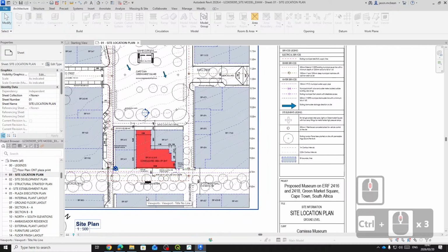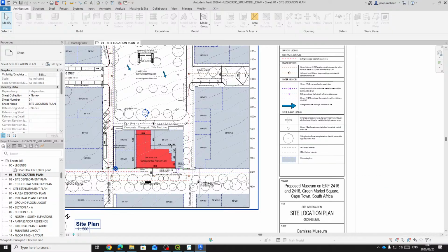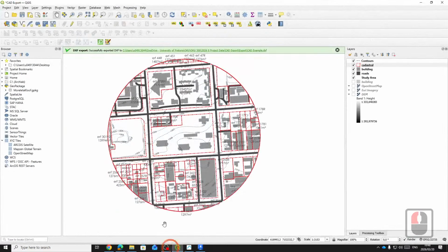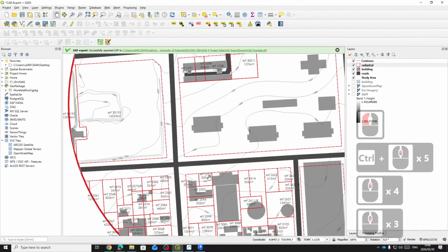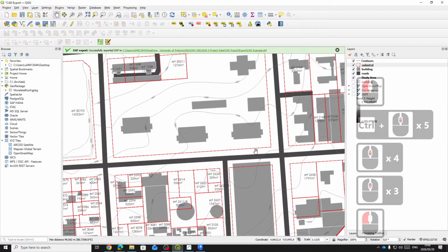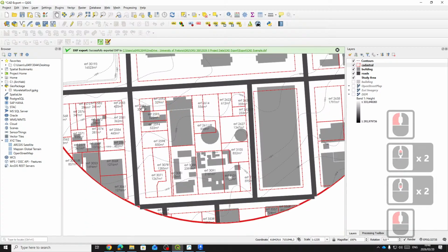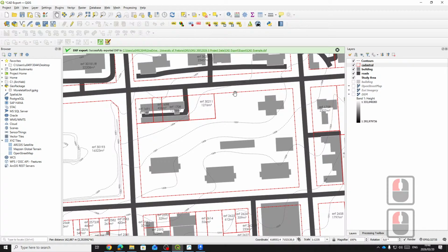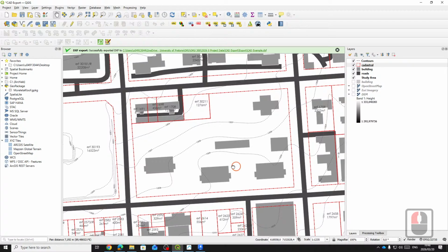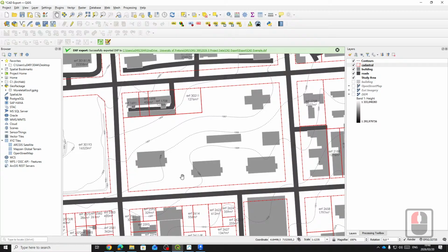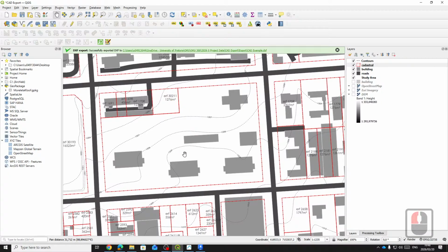I know that in design you were given a brief about don't worry about the cadastral information, but what I want you to understand is the road edges. So let me just jump into QGIS. The road edges, so the road reserve, which is this area along here, what I would ask you to do is maintain the street edge, but maybe consolidate the internal erfs. Maintain the street edge, because that edge is actually very important. So if we went back to the document, that road reserve, you have to maintain this street boundary. But the internal boundaries, you can reconfigure to suit your site.